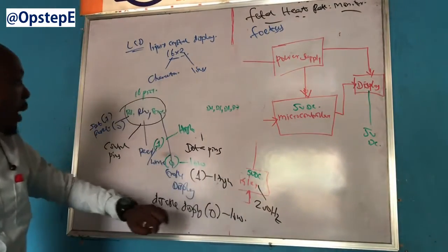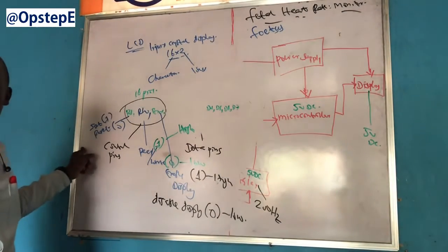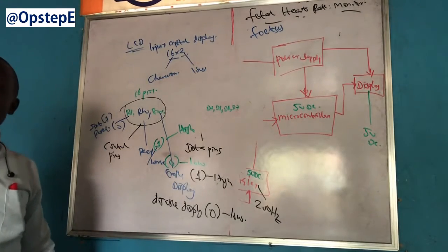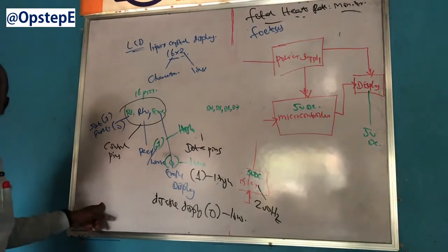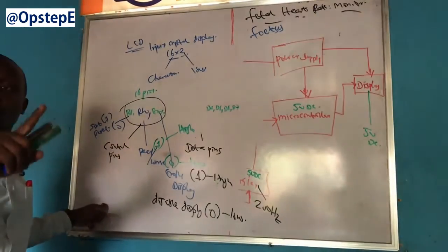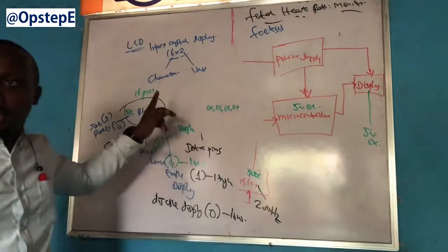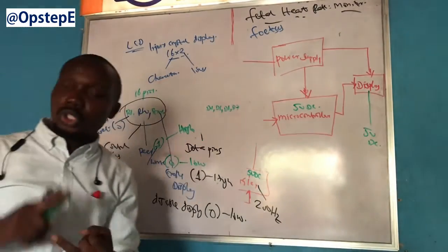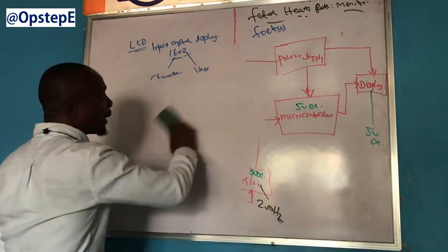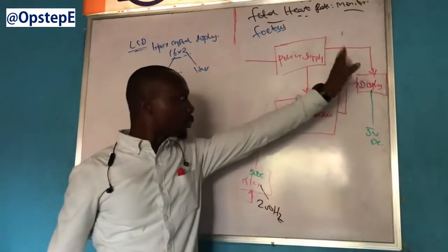While the LCD is going to have VSS on the cathode, on the K, and VDD on the anode, on the VDD pin, and then through a resistor to the backlight, and then a contrast control to the VE. We don't make use of D0, D1, D2, and D3. Please ignore. That's not about the display.